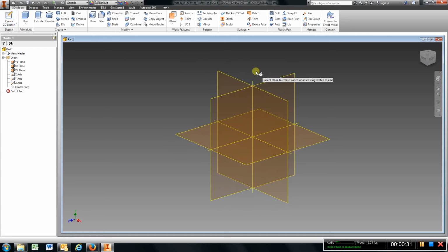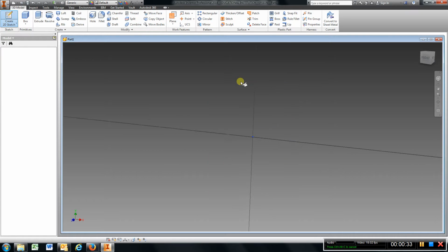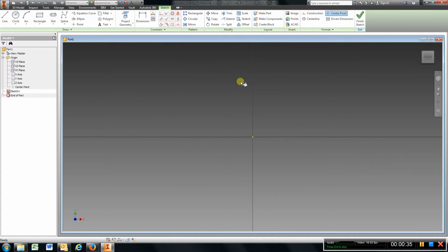Let's put a sketch here, and what I'm going to do is start at that very right end where you see the 3 inches. Sometimes I think it's better to model when you have angles. Go ahead and get those angles incorporated as soon as possible. So I'm going to choose the line command, come down here anywhere, drop in a 3-inch line, and again I'm going to center that up.